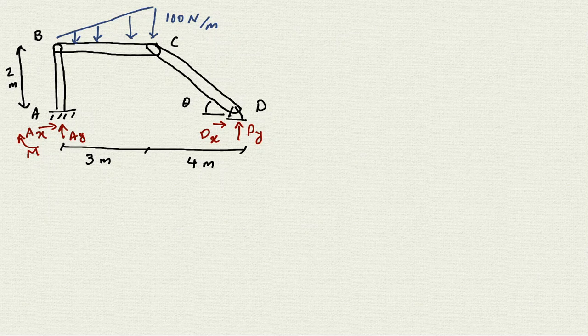It's going to be a two-member force. So instead of writing the D like that, we know that because it's a two-member force, that force is going to be along the CD. So instead of doing that, we can just remove that and say that force is going to be along that member. Whatever is the dx and dy is going to be along that member. So I'm going to leave it here, but eventually when I separate it, I put the force along that, so you will see how it comes out. So that's going to be our reaction.